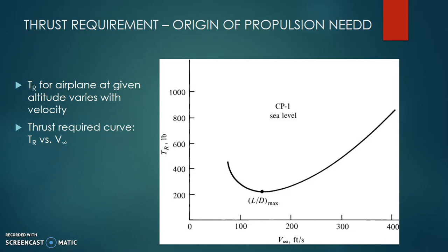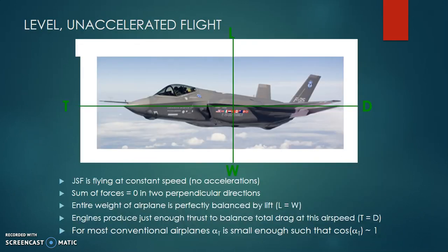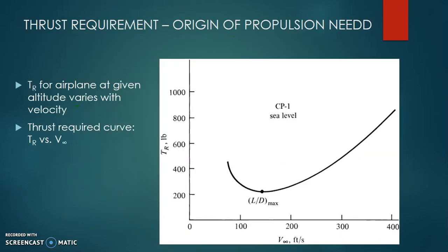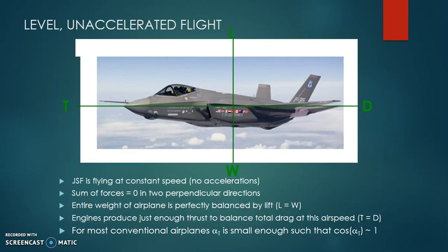That is also the reason why on the ground, initially at the start, you have to insert a lot of fuel to burn so that the turbine starts, and that's why you have these auxiliary power plants. As the velocity increases, the thrust required actually keeps reducing, which means there is a tendency where the high thrust actually starts coming down. This is the case because at these particular points, the drag and the lift are not yet balanced. So you remember these equations. Now when you are not in cruise mode but in increasing velocity maneuvers, the drag performs as a square function of velocity, and so does the lift.